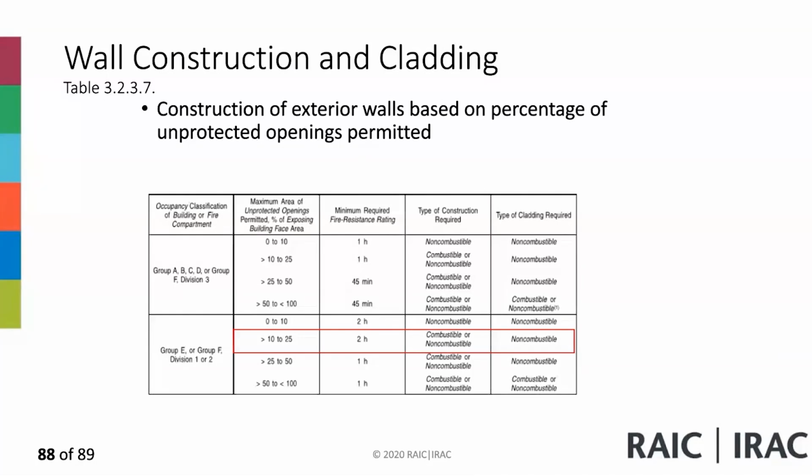If you are dealing with a street, then you can measure it to the middle of the street. If you're dealing with buildings on the same property, you measure the limiting distance to the measuring line between the buildings. And the setting of that imaginary line, you can discuss. Typically it's midway between the buildings, but if you want a different approach, you really have to talk to your local jurisdiction to address how you want to do it.